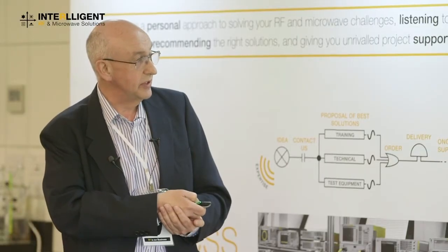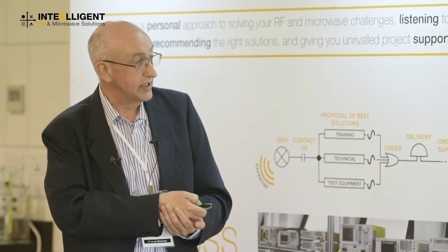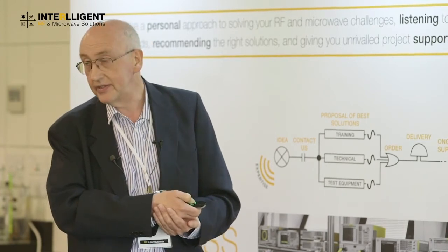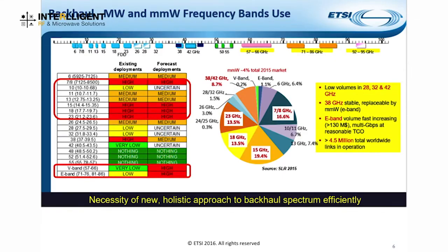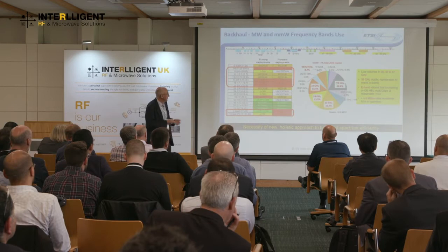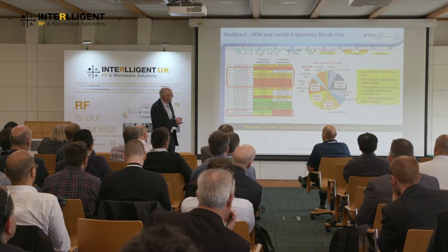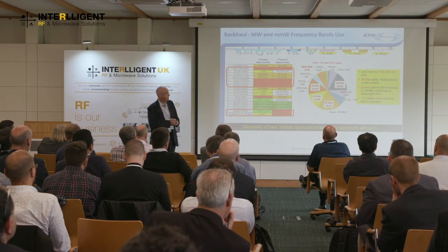The main interest in improving backhaul capacity is coming at the higher frequencies. Not so much V-band, because V-band is a bit of a free-for-all at the moment. The licensing situation is quite complicated. You'll hear it said that V-band is license-free, but that's not quite true. It's license-free in America and Canada and parts of South America. In most of Europe, the whole of the band isn't license-free. It's used for other things. And in certain countries like Russia, it's fully licensed. So 60 gigs is a bit complicated. And at the moment, just 0.2% of links are at 60 gigahertz.